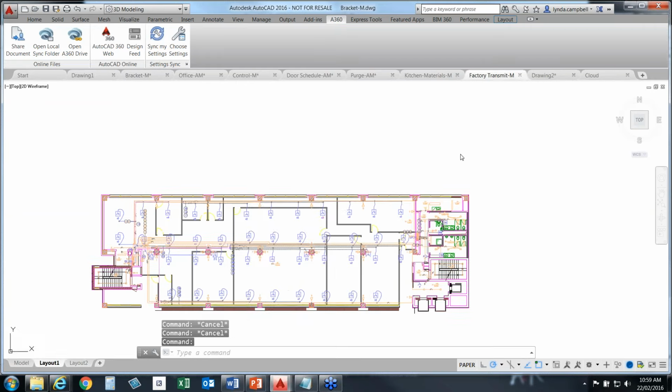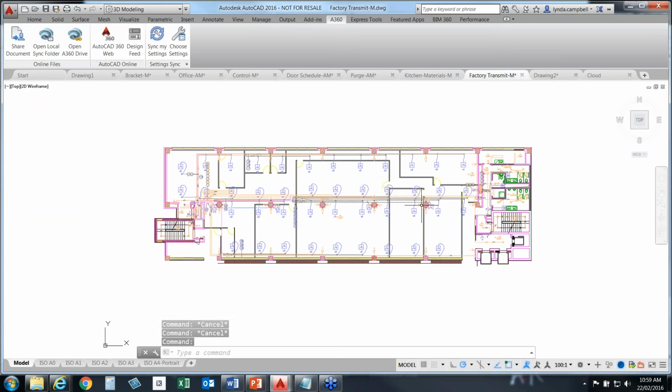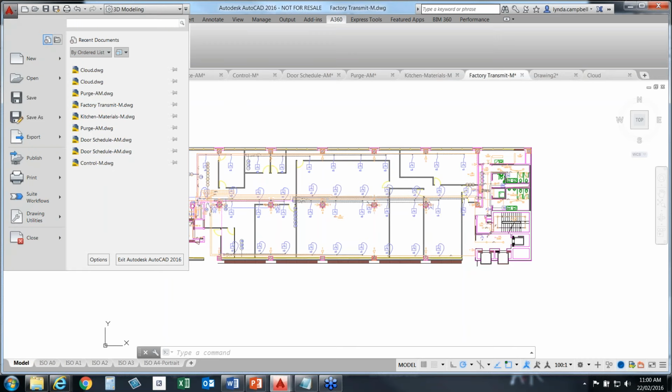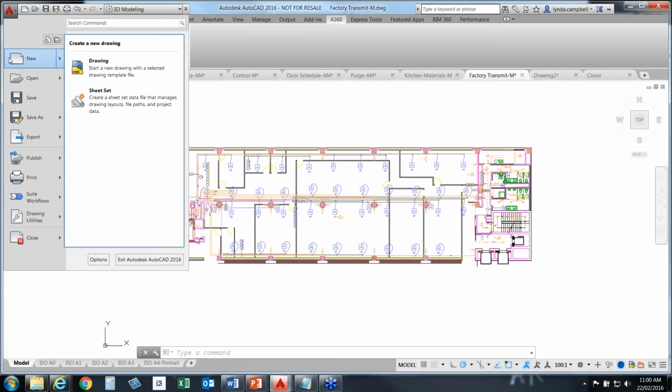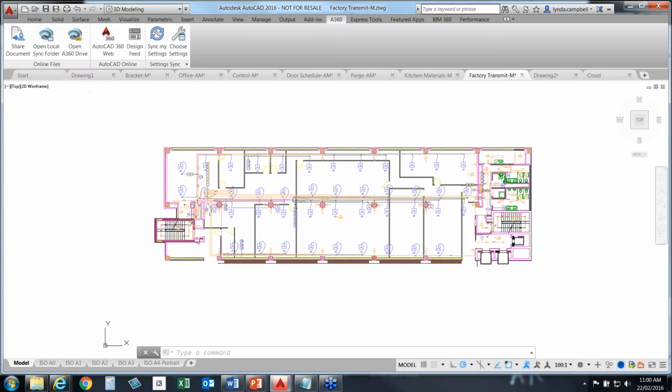those days that we get someone asking us to email a drawing and we use XREFs and we also want them to print it out according to our pen settings, etc., and our plot styles. For those of you that may have not seen this before, we have the eTransmit command. It's simply up in your application menu, publish.